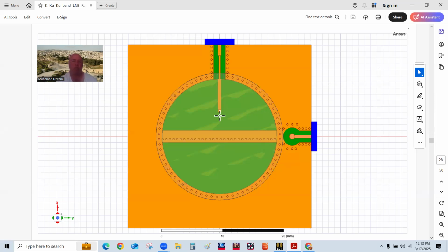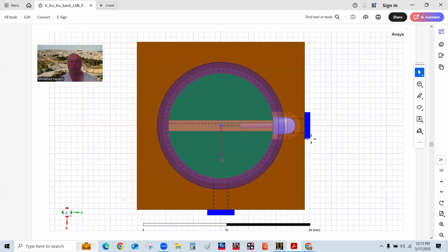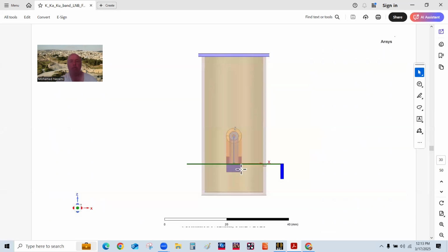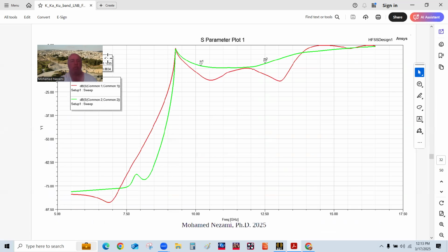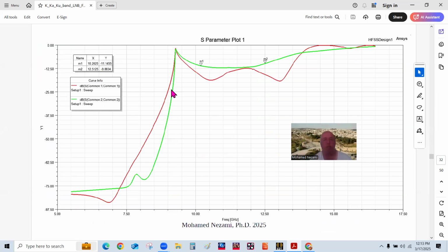And of course, I've got the other pole in here. And then this one here is designed exactly like a microstrip antenna. So I've got a 50 ohm feed line, and a higher impedance line section in here that is for matching. This is a quarter wavelength matching the probe in here. So here's another view of this. And then of course, for this particular design, I'll show you in a minute the response.